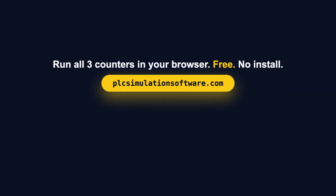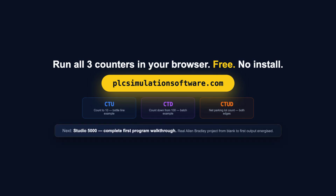The standard is shared. Run all three counters yourself at plcsimulationsoftware.com. The lessons on the free tier cover CTU, CTD, and CTUD step by step with each counter visualized live as the rung executes. You can watch CV tick up and down. Watch Q flip at the moment CV matches PV. Press reset and see CV clear instantly.